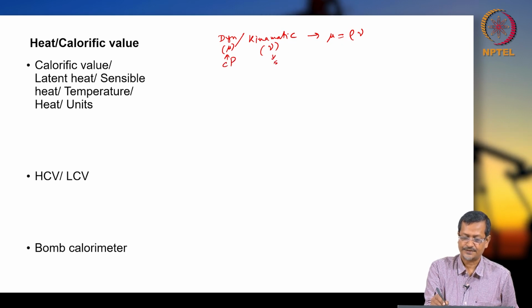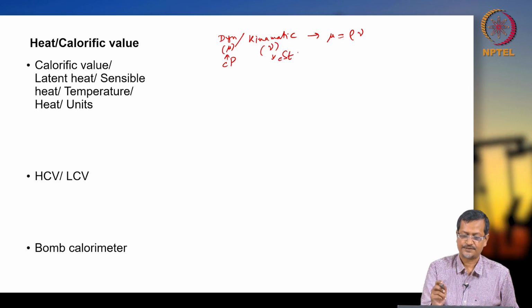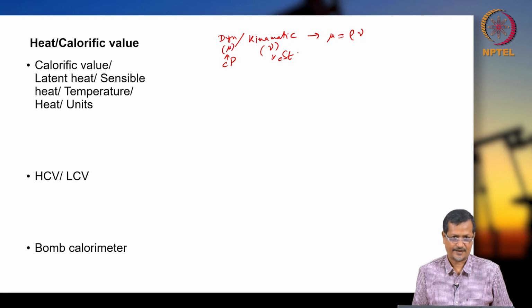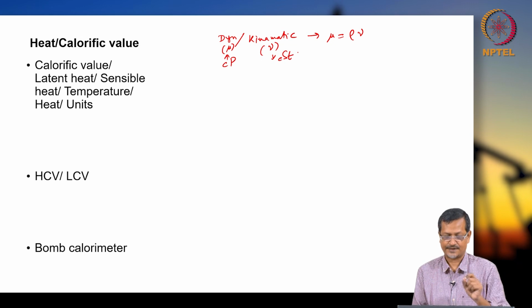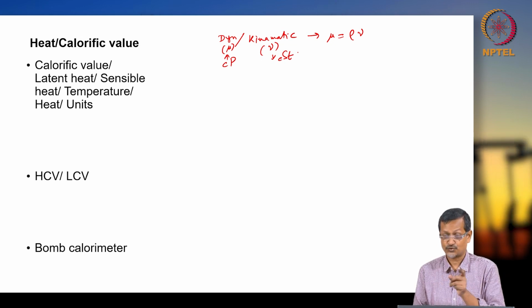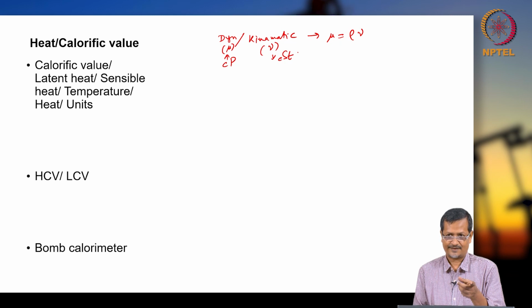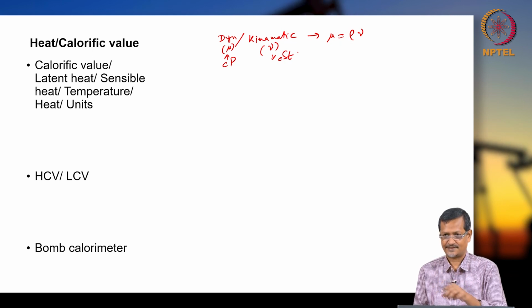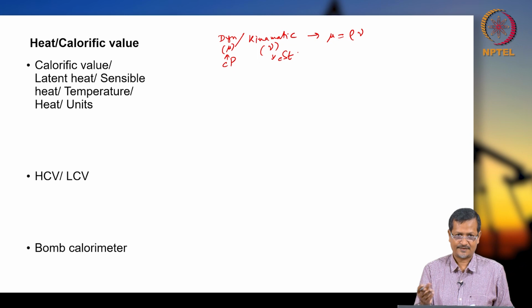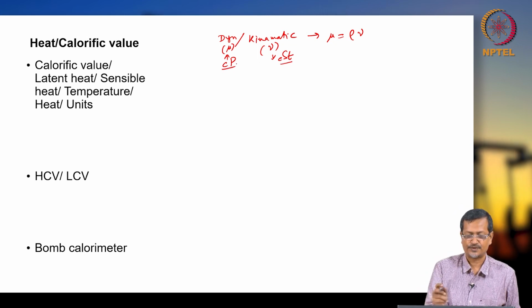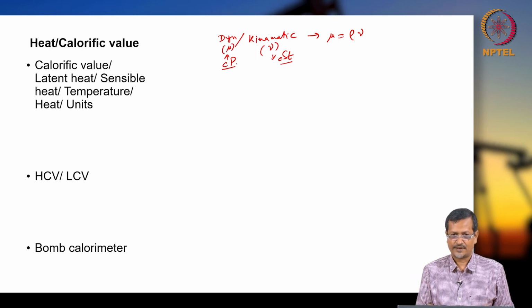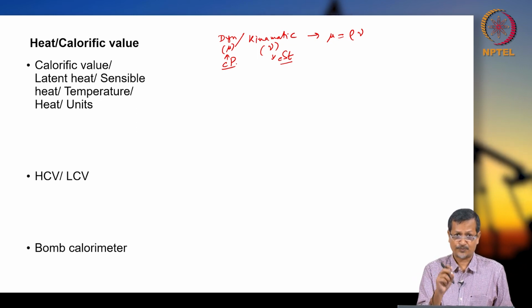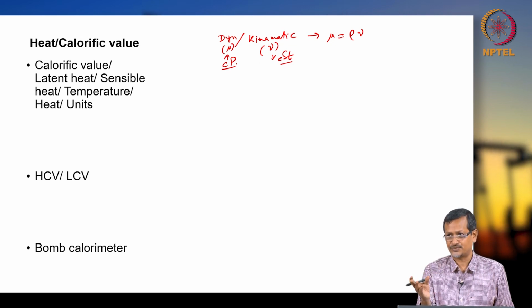And the units also: dynamic viscosity is in cP, kinematic viscosity is in cSt. Here you can see the small and capital letters again. So small c, capital P, for Poise, someone's name, a scientist. St is Stokes, so S is capital. C S t: c small, S capital, t small. So you should remember the units. You should not get confused when you are calculating something, and you should not put the wrong unit.